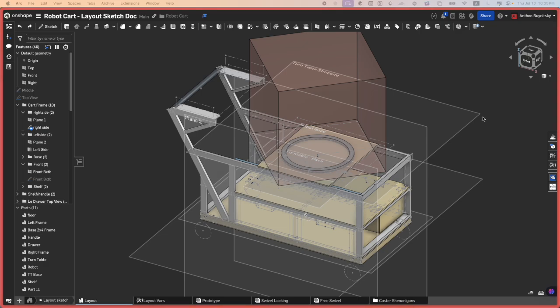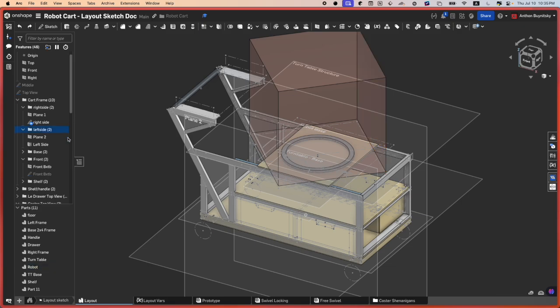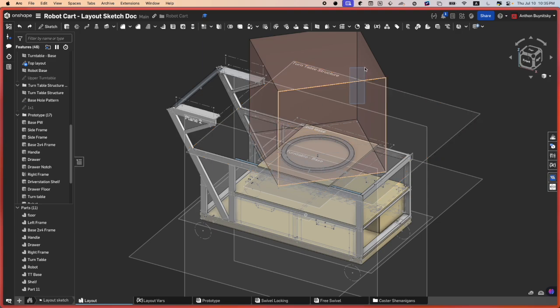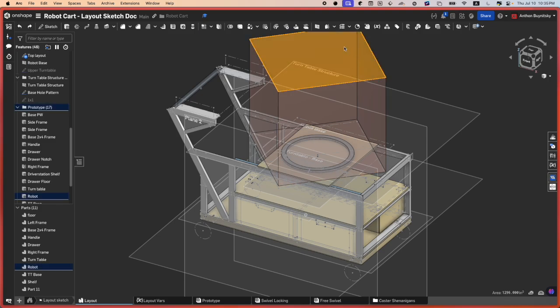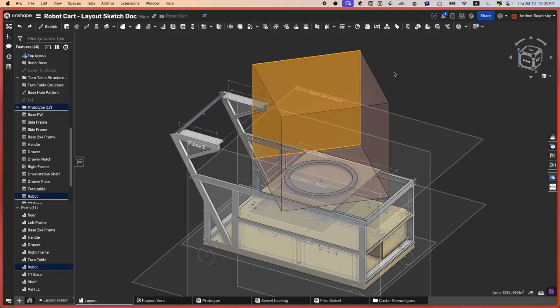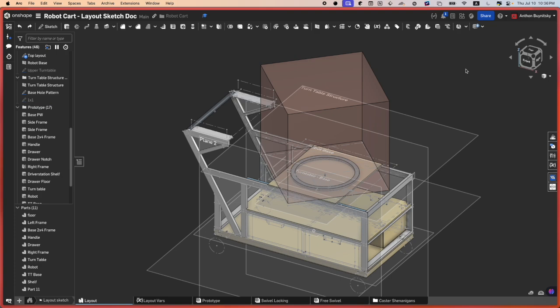So a rule for making your sketches changeable without having tens of thousands of errors after is using more geometric constraints than using the dimension feature. That helps a lot with the changeability of your sketches. So do that. Raj, any questions?